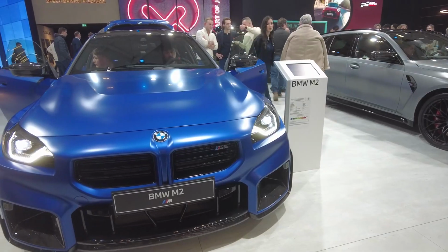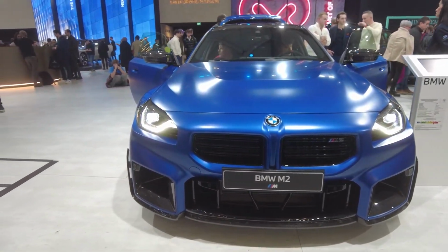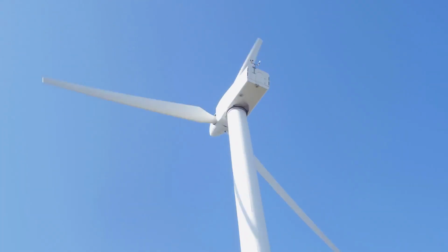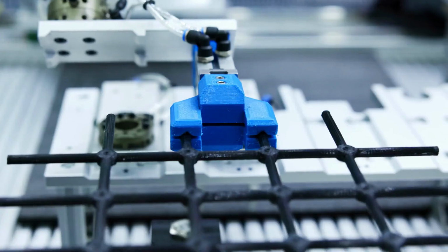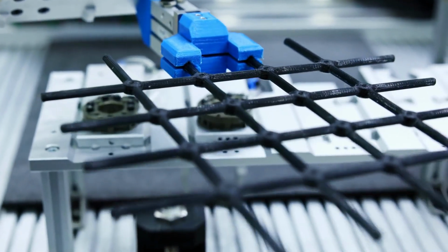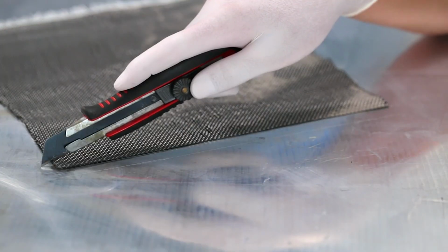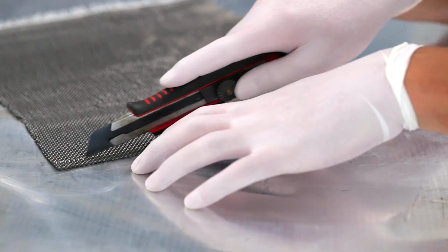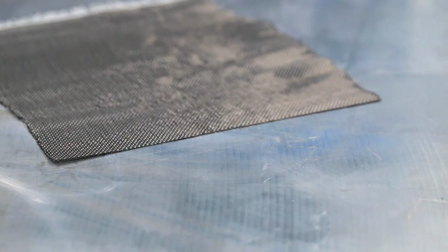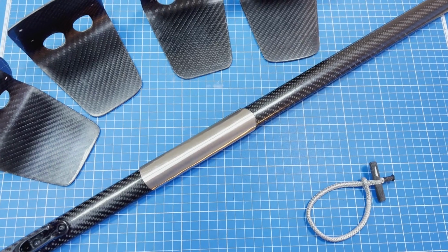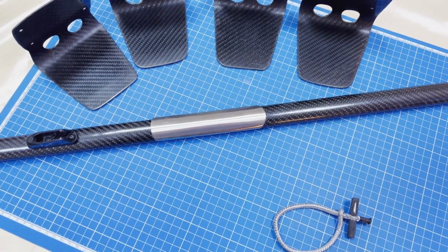Although carbon fiber offers extraordinary mechanical properties, it remains a relatively expensive material. The main reason lies in the complexity and energy intensity of the manufacturing process. The production of carbon fiber requires multiple stages that must be carefully controlled. Each stage, from polymer spinning to stabilization, carbonization, and surface treatment, must be performed under very specific conditions. Even small deviations in temperature, tension, or processing speed can affect the final quality of the fibers.